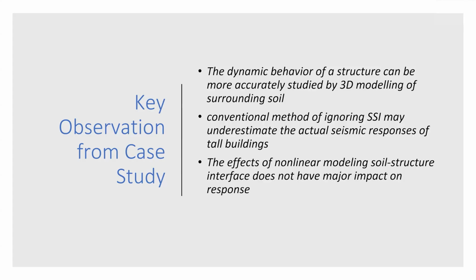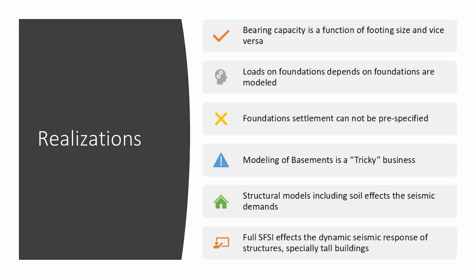But if the structure was very stiff, or a small building, the difference will be much more significant. Let's say a nuclear power plant or something like that, it will be much more significant. Because the structure is so soft, what happened in the foundation gets absorbed. So you can do all of that, but maybe you don't need to do the last one. We wanted to find out whether you really need to do that or not, and the conclusion was not really. It's good enough to do at least the minimal soil structure interaction using springs and so on.